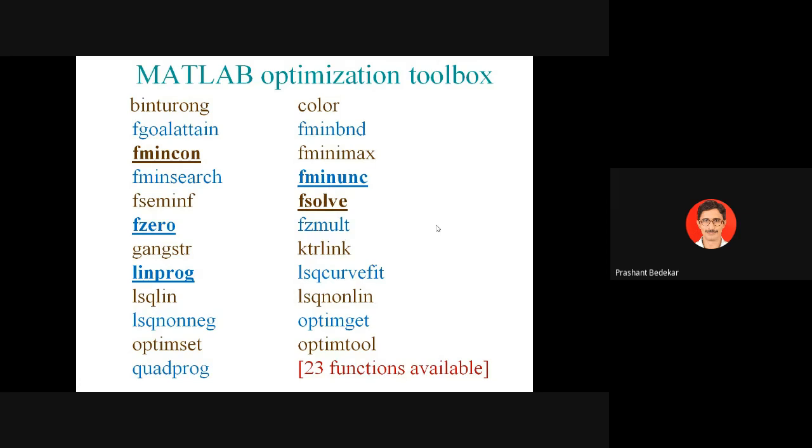So what I wanted to say is that before application of any MATLAB optimization tool, we should first of all convert the objective function into minimization type. Then we should convert all inequalities into less than or equal to type. And then only we should proceed for application of the tool. So keep this in mind.